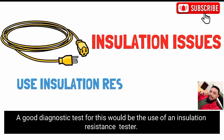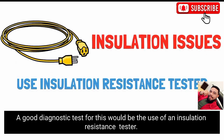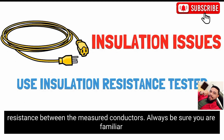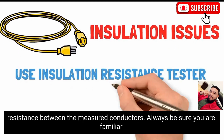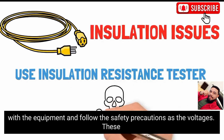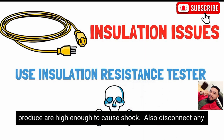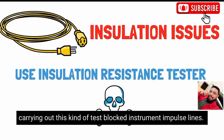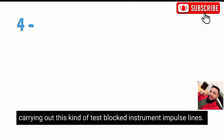A good diagnostic test for this would be to use an insulation resistance tester. This piece of equipment applies a voltage to the cores and measures the resistance between the measured conductors. Always be sure you are familiar with the equipment and follow the safety precautions before doing any disconnection. Also disconnect any sensitive equipment such as barriers or instruments before carrying out this kind of test.